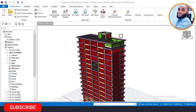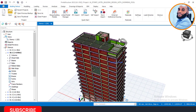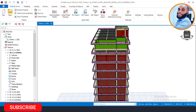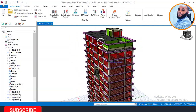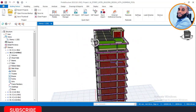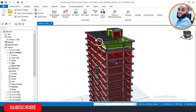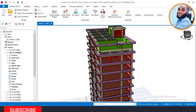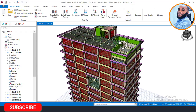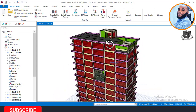Okay, so when performing a structural design for a high-rise building in ProtaStructure, there are two methods you can use: either the finite element method or the yield line method. The most common and most conversant one is the yield line method. So we will be using the yield line method for the design and analysis of this structure. But before we use it, there are some settings that we are meant to do, and right now I will take you through those settings.